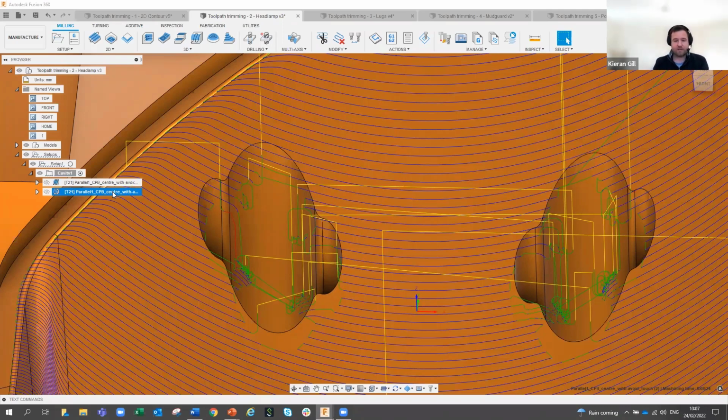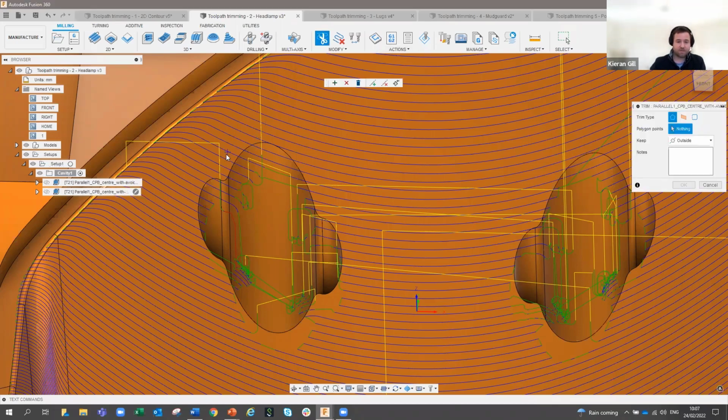One, it's really not adhering to my contact point boundaries. And what this means is that the tool is diving down vertical walls, which could damage the tool, damage the part, and even worse, permanently damage the machine tool. Now, in some circumstances, we can try to overcome this by editing the strategy to include touch and avoid surfaces, but this doesn't always give us an acceptable result and can often result in lengthy delays in surface selection and calculation time. Now, toolpath editing aims to make this process significantly more efficient.